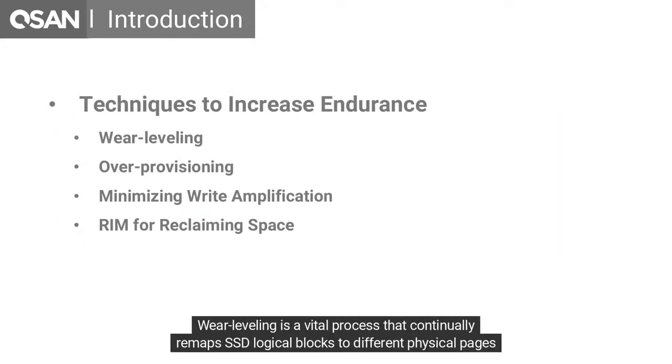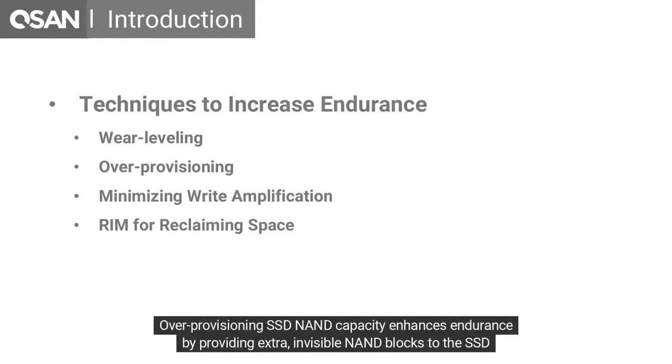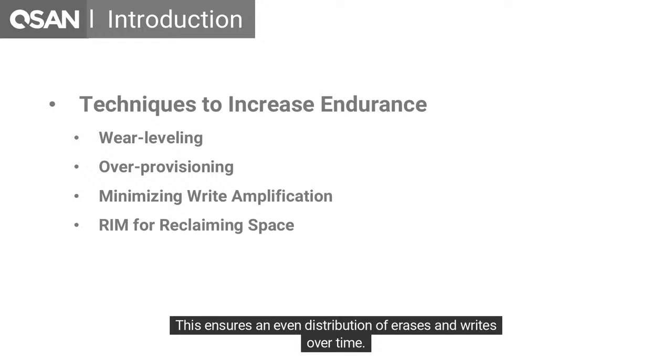Wear leveling is a vital process that continually remaps SSD logical blocks to different physical pages in the NAND array. This even distribution of block erasing and writing prevents premature wear, maximizing SSD endurance. Despite being a background task affecting performance, wear leveling is crucial. Over-provisioning SSD NAND capacity enhances endurance by providing extra invisible NAND blocks to the SSD controller. This ensures an even distribution of erases and writes over time. While a larger spare area enhances controller efficiency, it also increases costs.